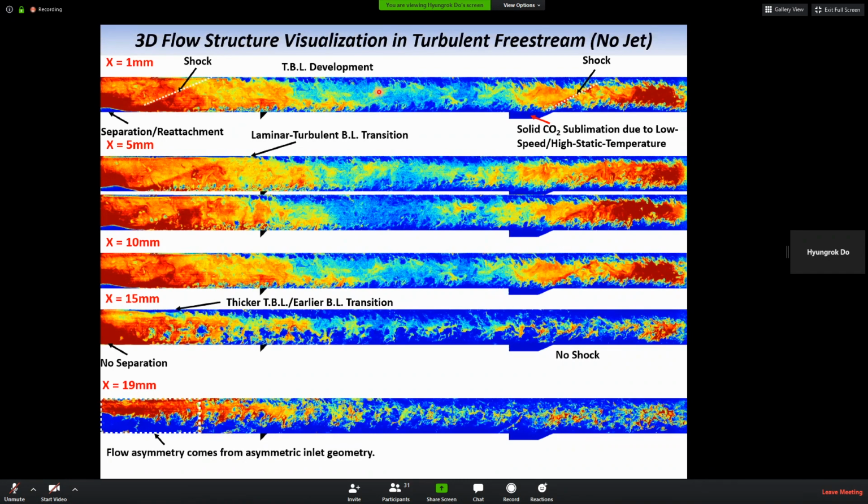particularly in this case, the flow speed is Mach 4.5, and the flow is so fast and highly turbulent, and the evolution of the flow structure is quite fast. So to take the snapshot of the flow structure, your measurement time or laser diagnostics time should be quite short. So the only option you can use is the optical measurement method in this case.